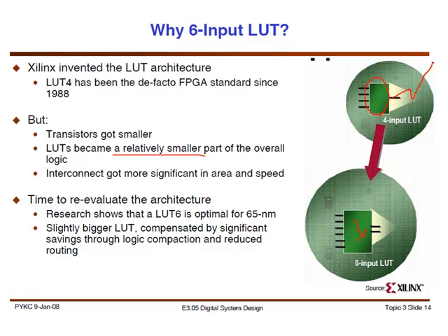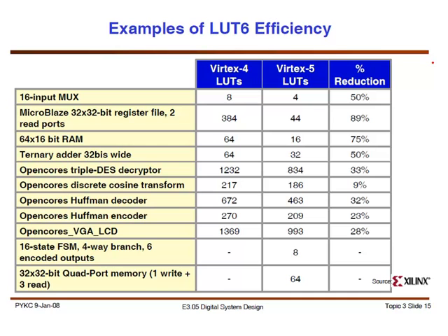In today's world, with today's technologies, 4 LUT is not going to be useful. You need at least 6 LUTs, and that's how FPGA companies adapted, and they started using larger LUTs. And if you think about increasing it to 6 LUTs, basically the Virtex 5 family started using 6 LUTs.